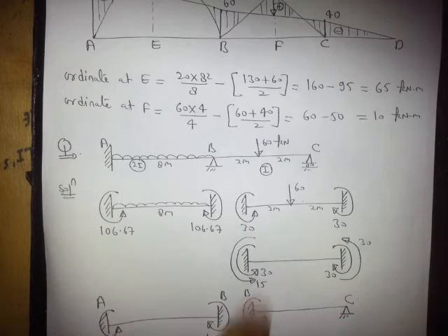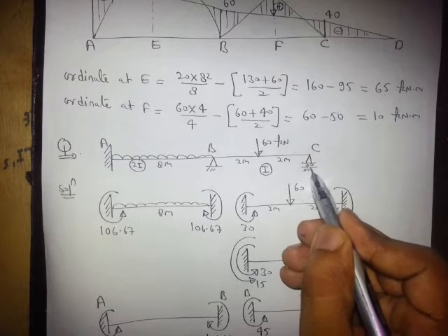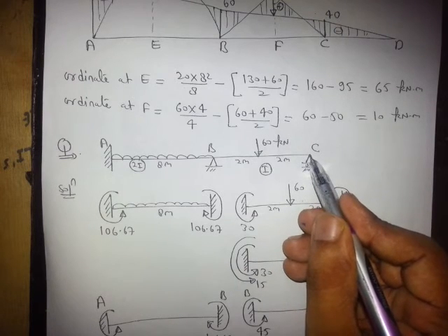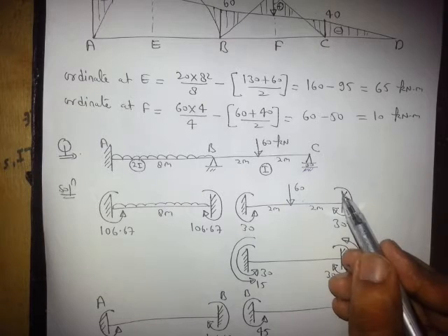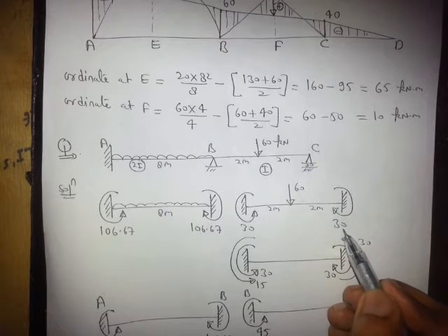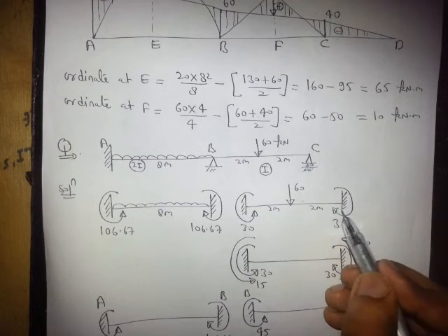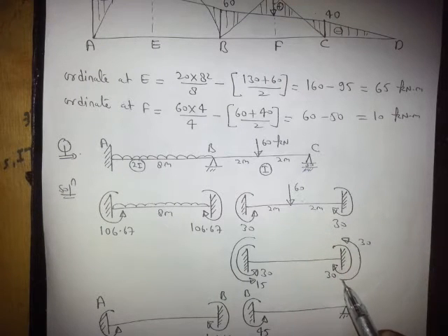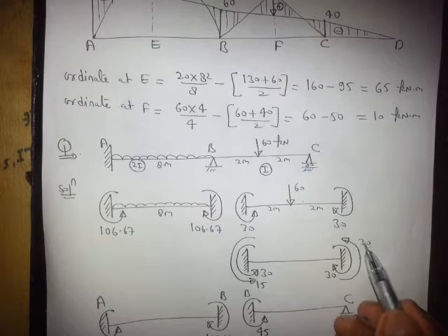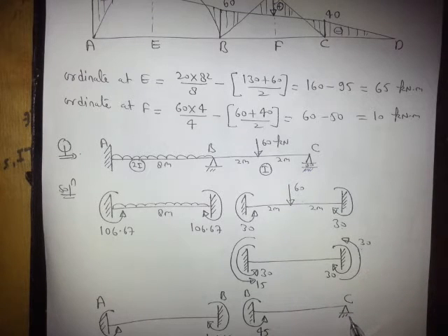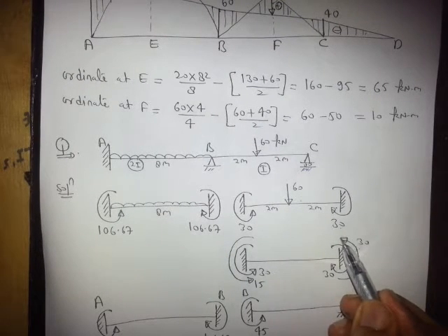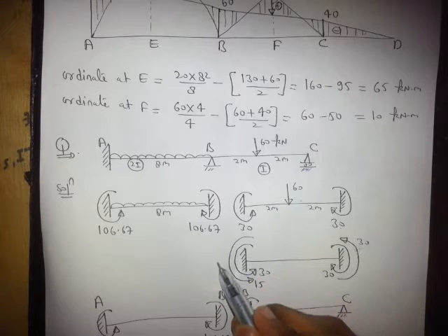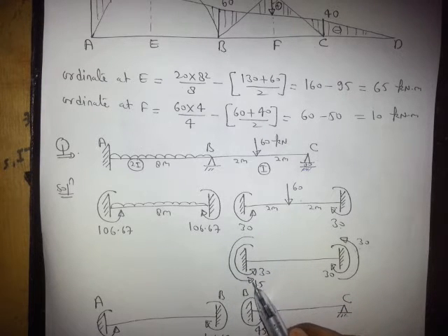Now dear friends, as I know that this is purely hinge end, I should make a correction. I have already calculated moment as 30 here, but here the net bending moment should be 0. So 30 is clockwise, so I will apply 30 anti-clockwise, so net will be 0 and this end will become hinge end, means net bending moment is 0. But as soon as I apply 30 in this direction, half in the same direction will be transferred to the far end.